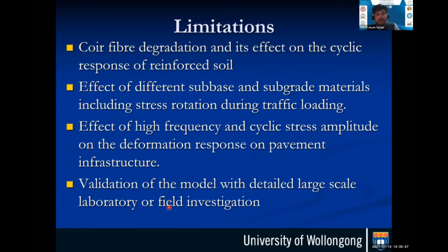Limitations: I need to be very careful about the limitations of application of these Coir geotextiles for different infrastructure construction. The first thing is the coir fiber degradation and its effects on the response of reinforced soil. So it is very critical that we develop a model which captures the degradation of the coir fiber, and that needs to be integrated into any model to capture the short-term and the long-term perspective. If we are able to predict the time frame up to which this material is going to perform, that is exactly what a practicing engineer will be looking for before applying this